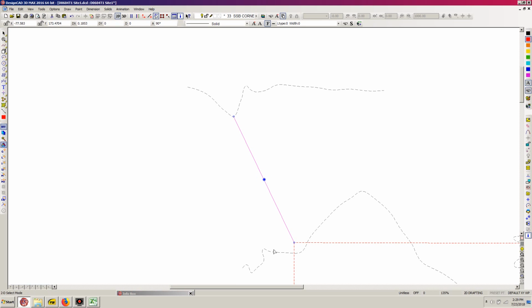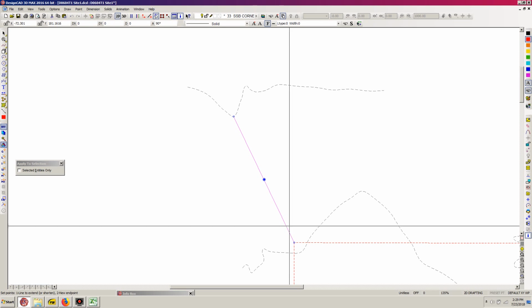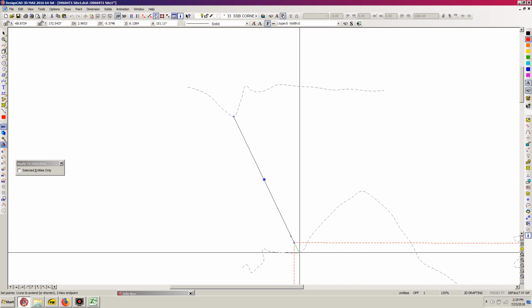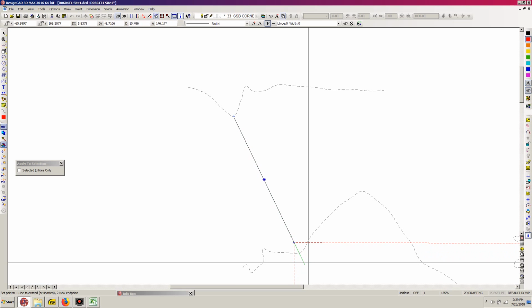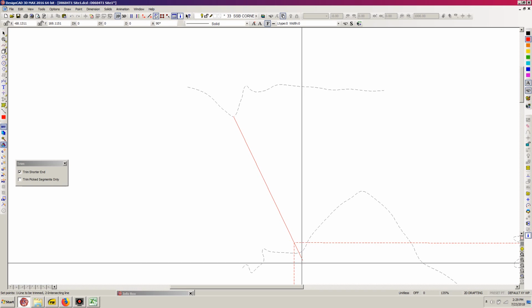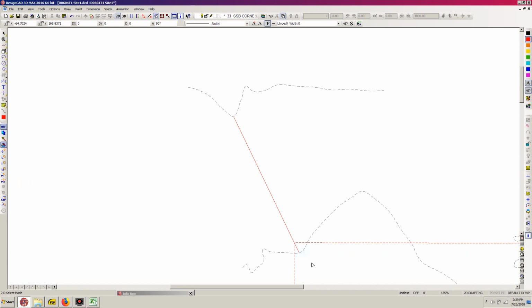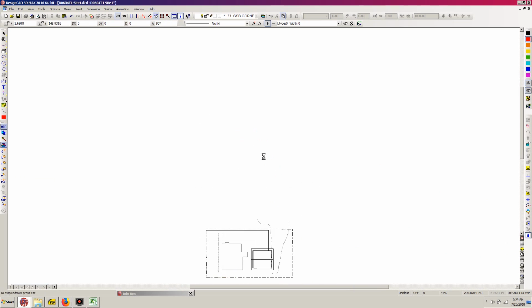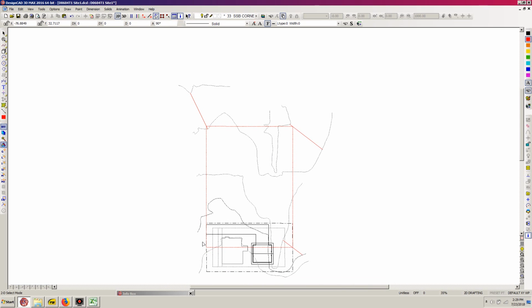And now I'm going to select that line that I just did and use the extend command, which is the Shift dash command. And now I'm going to trim, hit escape, and I'm going to trim this to the topo line. E, and trim to the topo line. Okay, so now I have that one set, and I'll have one additional corner line that I need to do, and that's down here at the southwest portion of our 150-foot slope calculation area.